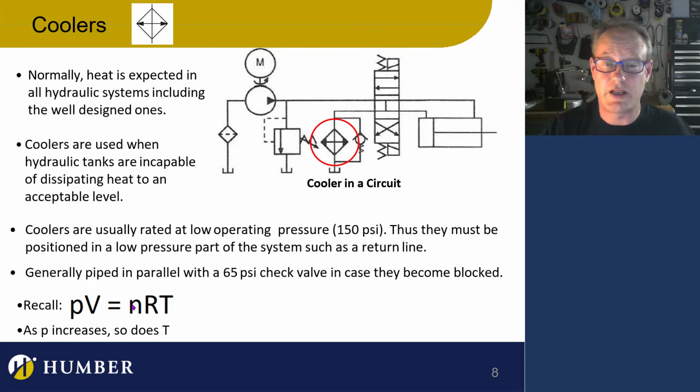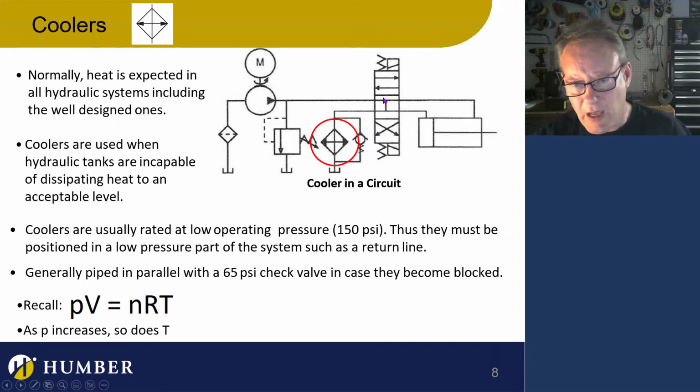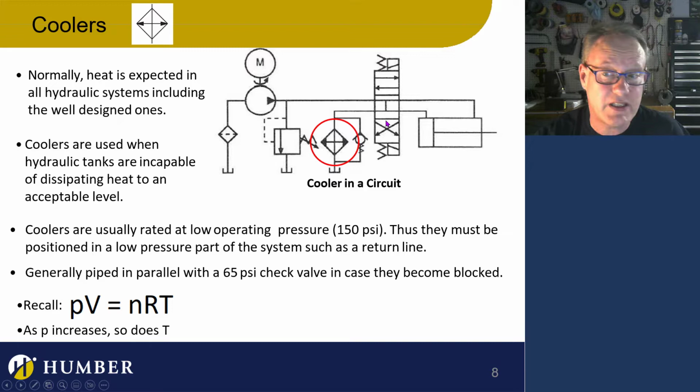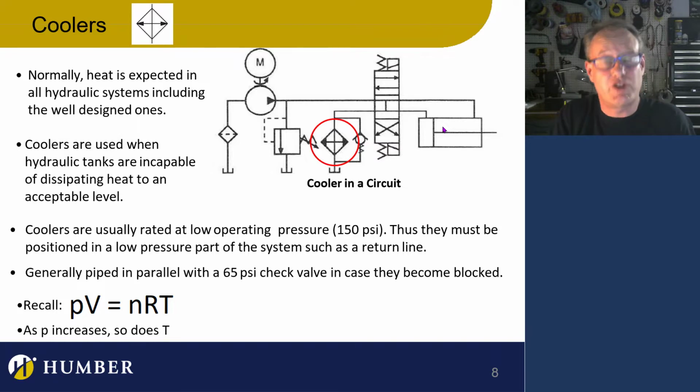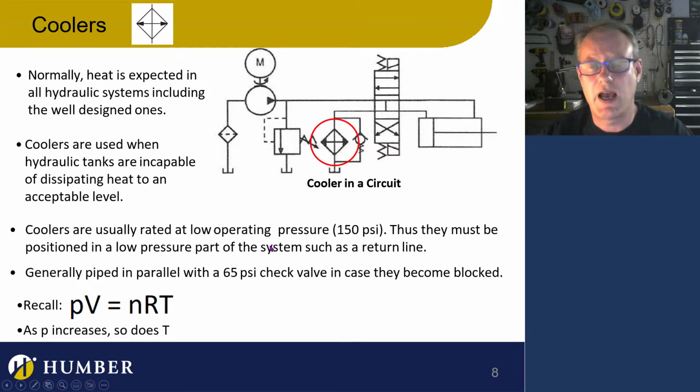Essentially, what's going on is that as the fluid is going through this line, through the DCV, through the actuator itself, I'm going to be losing pressure. The energy there is actually put into heating up the fluid, and that's why we have so much heat. So we have to put coolers in. Pardon me, I said have to. In some cases we do, in some cases we don't.